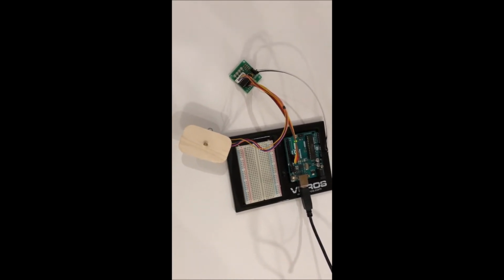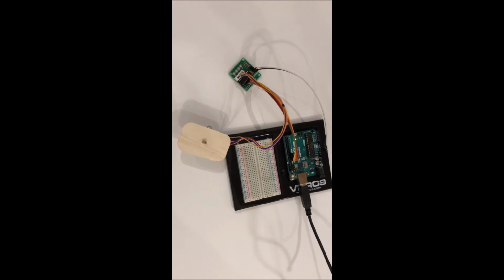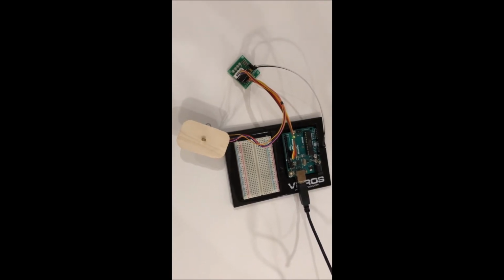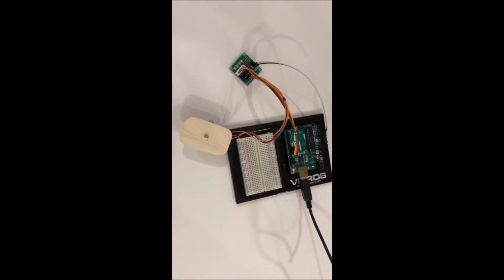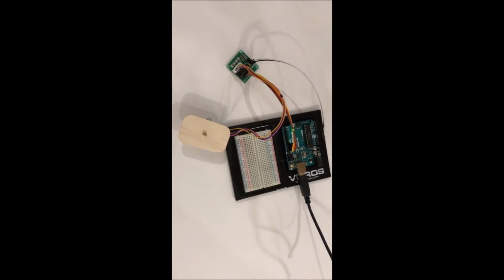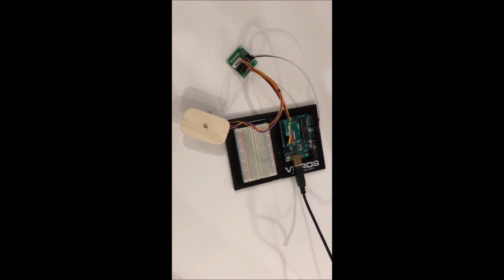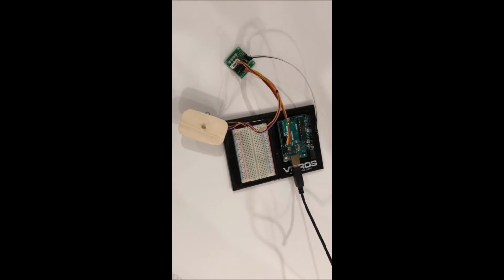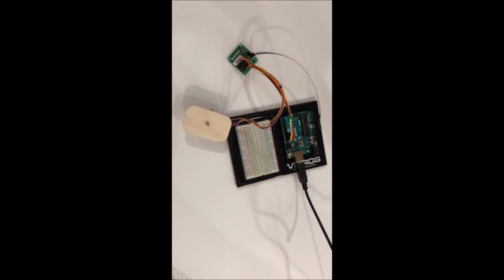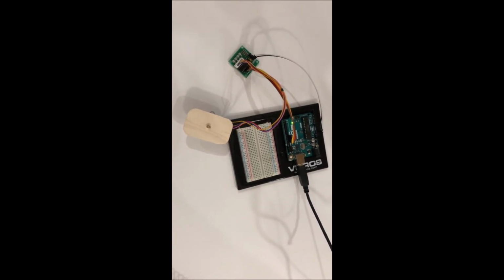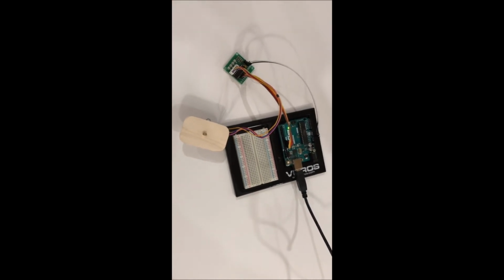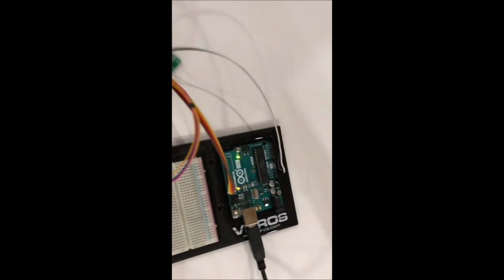So, what are some more difficult things? Well, it might be the code. I can eliminate that because I was just running this code and I know that it worked fine. So the only thing that's changed is I've changed the wiring on the stepper. I had to unplug it to move it, and then I've plugged it back in again. So most likely the wiring is the problem. So now I'm focused down on the wiring and I can check that out.